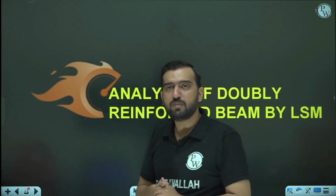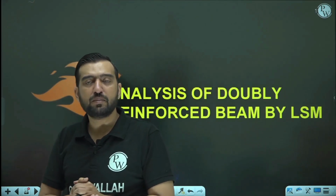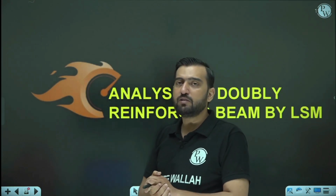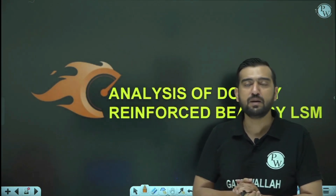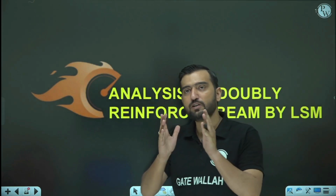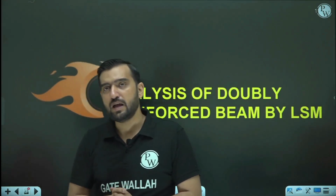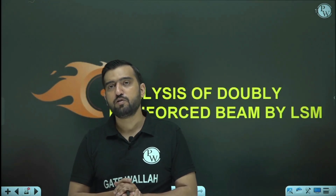But if the size of the beam is limited and the grade of the material is also fixed, in that scenario, what can we do if we want to resist a higher amount of bending moment in a limited cross section and with a particular grade of steel and concrete? Then, my dear friend, we have to go for a doubly reinforced section.